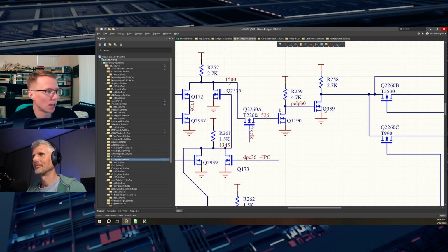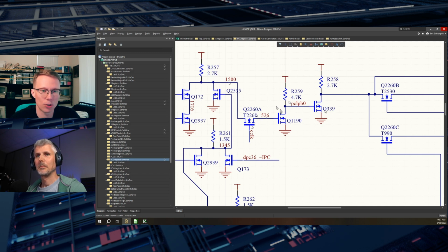The next clock phase, I should say the next half clock, this C clock line turns off and that transmission gate opens up. The state of this transistor stays the same because there's charge that's been loaded onto the gate of that MOSFET, and there's nowhere for it to go. It'll slowly drain away, leakage currents and stuff will slowly drain it away, quantum tunneling effects, that kind of thing. But for the most part, it sits there and it just stores that state.